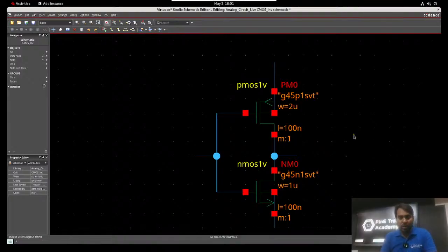Okay, so till now we designed one, we are taking one PMOS from the instance, we are taking the NMOS from the instance, and we connect source and body. Why? Because we don't want any VTH effect, that is body effect. The body is connected to the source, VSB is 0, because VTH is equal to VTH naught plus gamma times (under root 2 phi F plus VSB minus under root 2 phi F). So if VSB is 0, VTH is equal to VTH naught. So I don't want any body effect, so just like this.